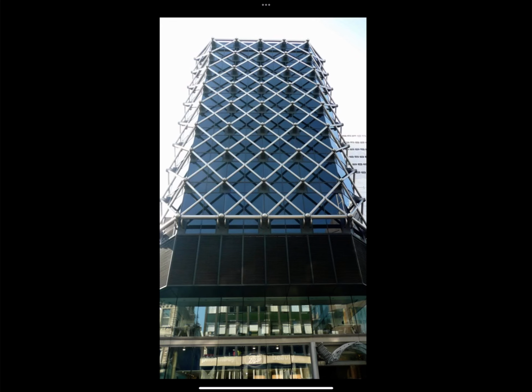So we can encase steel in concrete, we can wrap it with expanded metal and wet plaster, we can wrap it with gypsum board or drywall, we can spray on fireproofing, we could have a water-filled structure, we could design a flame shield, or we could use intumescent paint.